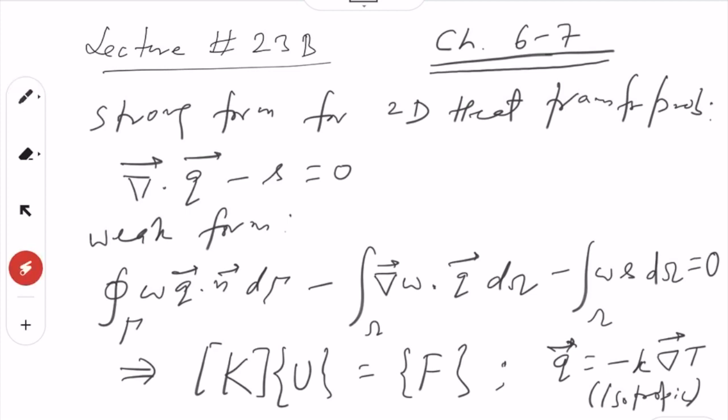Okay. So, the T term is there here, and we have to assume some test function for T, where T is a function of x y basically. So, this is 2 dimensions, so x y come into picture. T is not just a function of x, but also function of y. So, T x y. We have to assume the test function T, and the weight function W also will be 2 dimensional now, and that is the only difference.